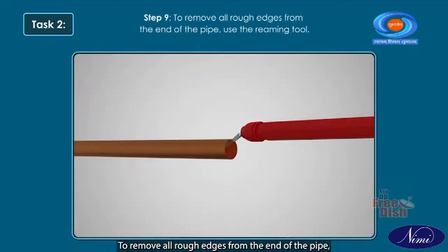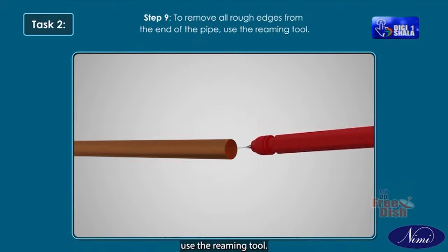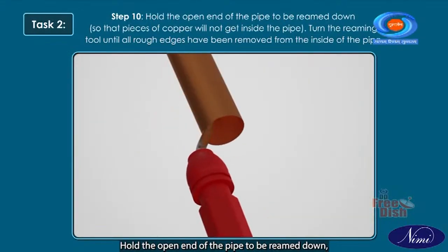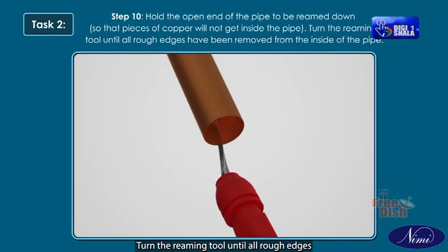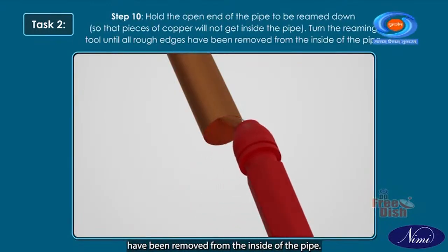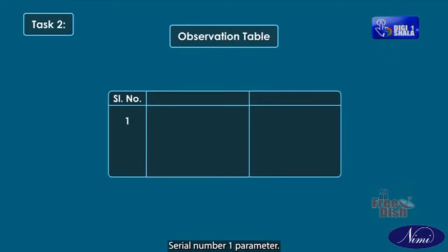Step 9. To remove all rough edges from the end of the pipe, use the reaming tool. Step 10. Hold the open end of the pipe to be reamed downward so that pieces of copper will not get inside the pipe. Turn the reaming tool until all rough edges have been removed from the inside of the pipe.